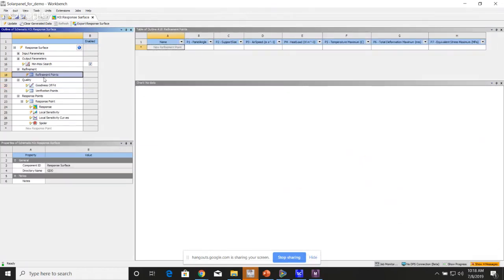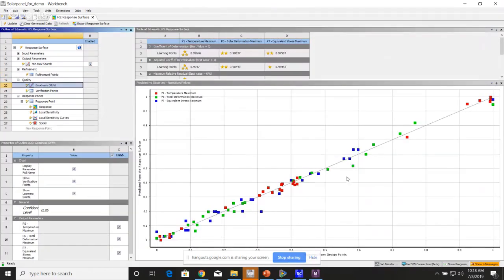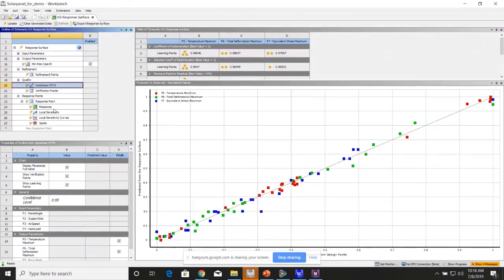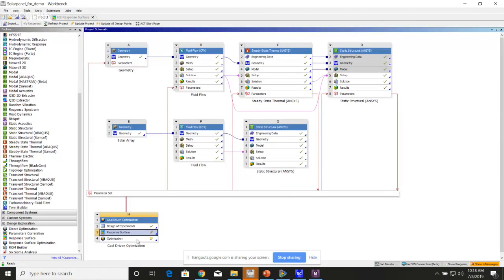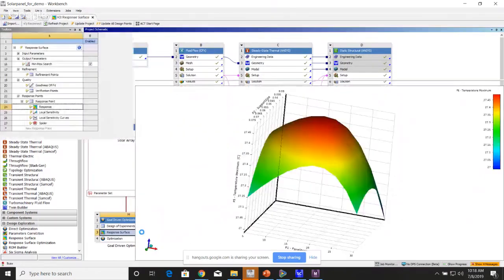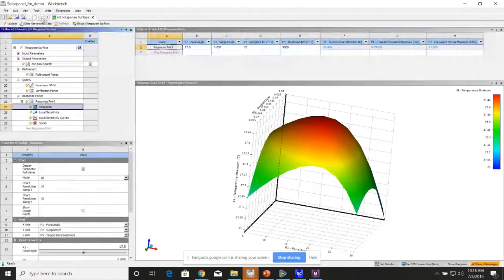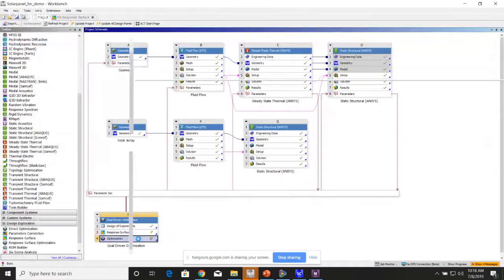We can add refinement points to better tune the fit. The goal is to get a response surface or an equation that'll realistically interpolate between all of our input and outputs. Finally, once we have this equation, it becomes easier to tackle this optimization problem.